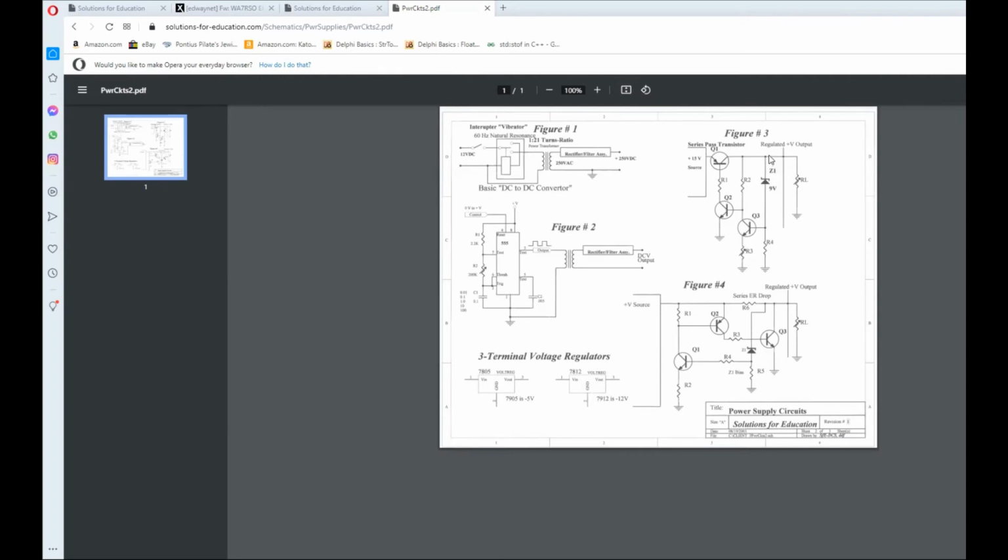So what happened is when the voltage up here starts to increase, and we don't want it to, this comes down through here and says conduct more, conduct less, making this voltage fall back down to where it's supposed to be. So this is a really good tight regulation system.